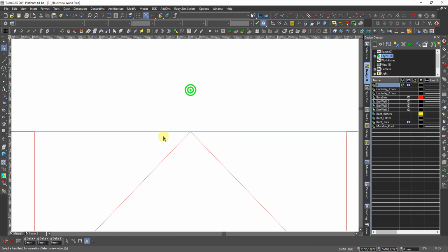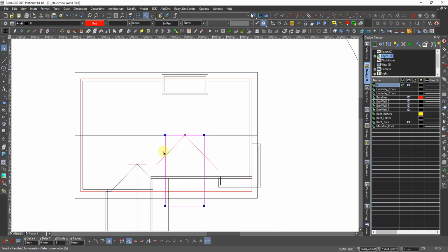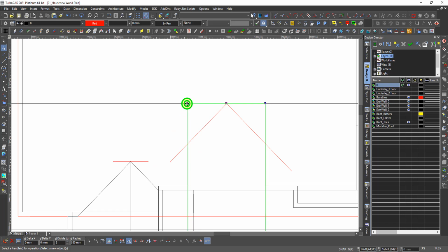So I take edit 2, and take this polyline, and I press here, Control, and adding a node, but they don't care about the snapping. Okay, so there's no snap. Take this and move to V. There it is, and this thing here I can take down here to its own intersection, pressing I, and the same thing here, down to its own intersection, and pressing I.